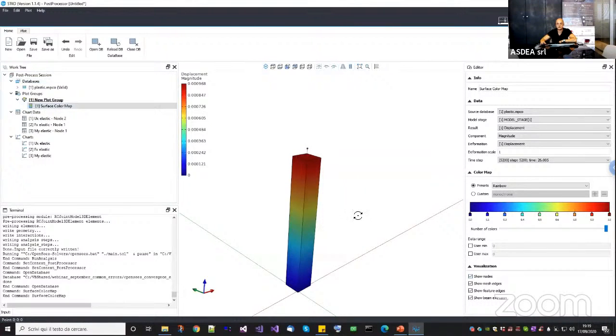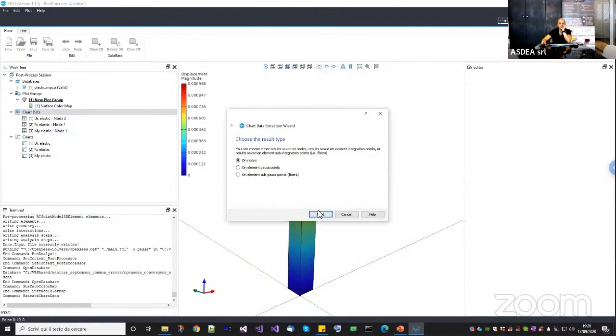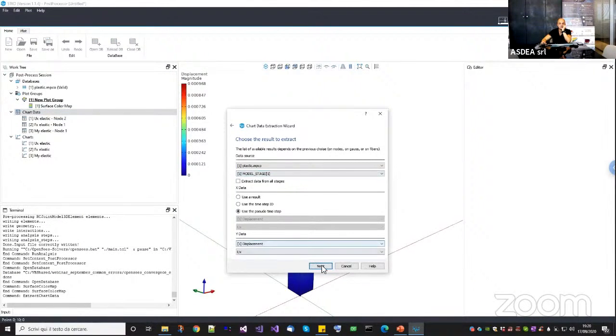Let me show the node. First of all, here, do not make the error of using the rubber band selection because here you have two overlapping nodes because here you have the plastic hinge, okay? So you can click on it, and since you have two overlapping nodes plus the zero length element, it will ask what node you want to select. Now in my case, I want to select node 2, the one with the smallest ID, because it's the one that you have in STKO, and it's the one where you apply the load, okay? So number 2, and here I want to extract displacement.